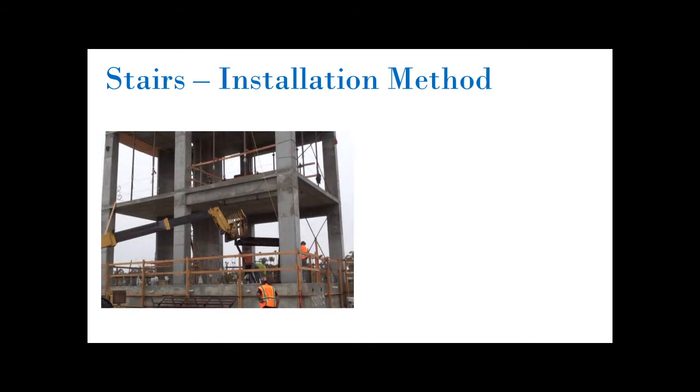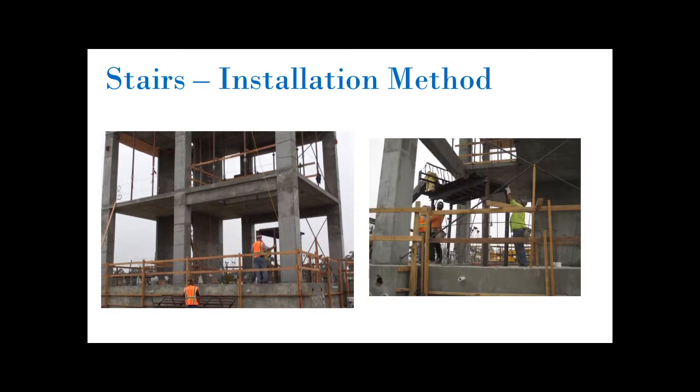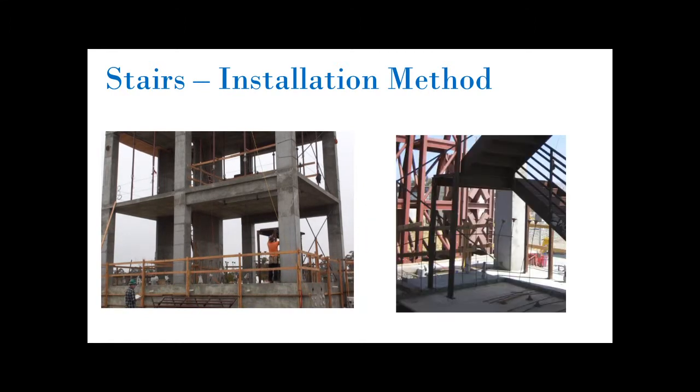During installation of the stairs on the first level, the lower flight was connected via a bolted connection to the floor slab at the ground level and to a landing supported vertically by 4 landing posts. The ends of the 4 posts were welded at their bases to the steel embeds, which in turn were connected via bolts to a concrete slab.